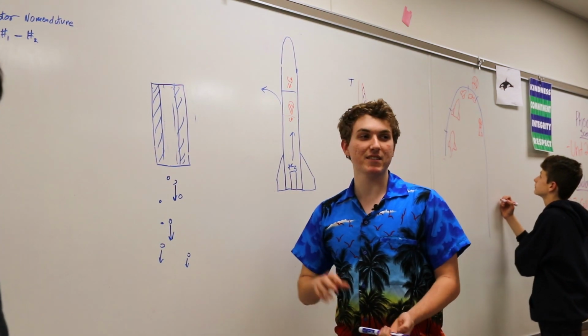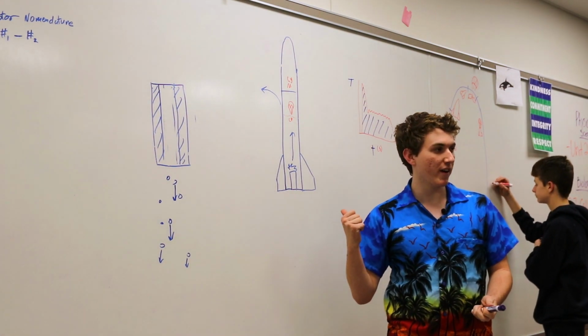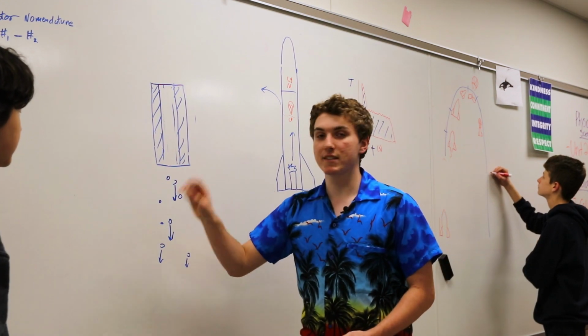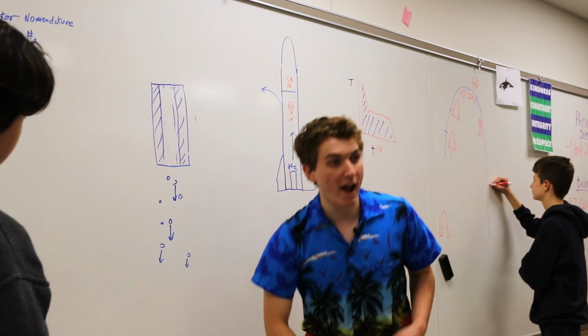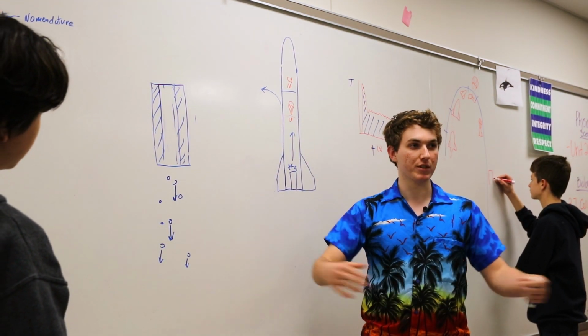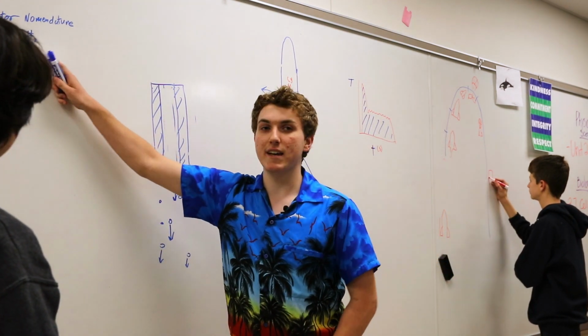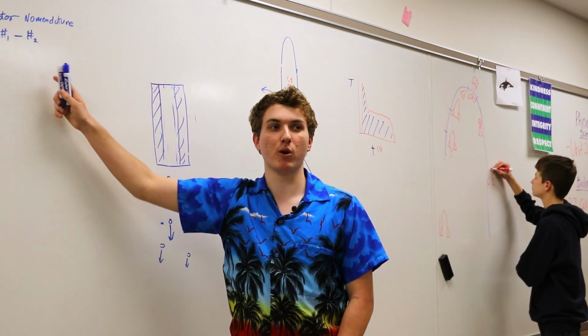That doesn't tell you the exact number. You have to look at the thrust curve to find that, but it gives you a very rough idea. The second number is your average impulse, or the average amount of thrust that's applied over the time. And the last number is how long until after the motor finishes burning.